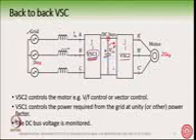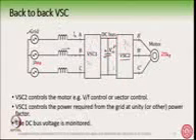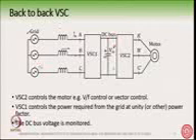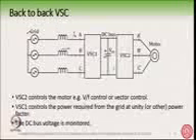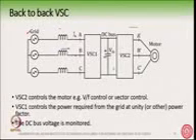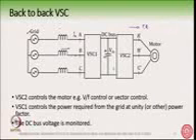So let me talk a little bit about the reactive power. Remember, reactive power is a degree of freedom here. Suppose we take a condition where this motor is taking some P and Q, but VSC1 is taking only P and the Q is 0. When can it happen? If you can make VAG and IA be in phase.